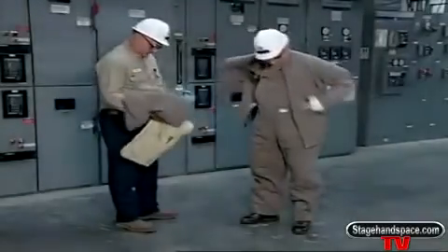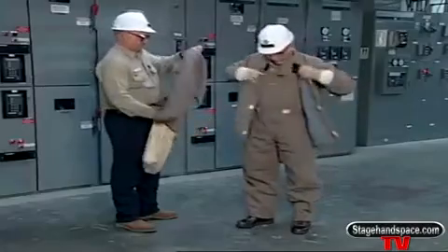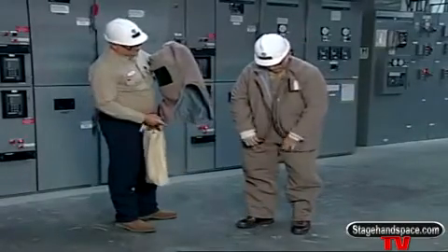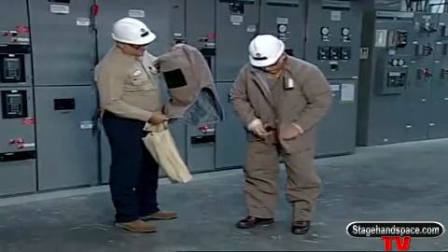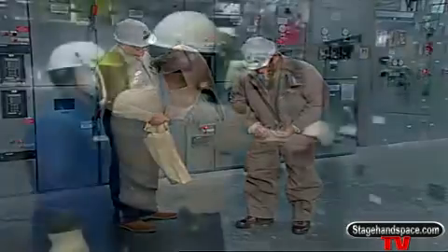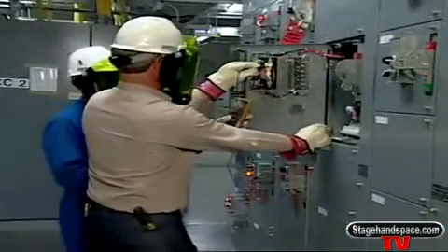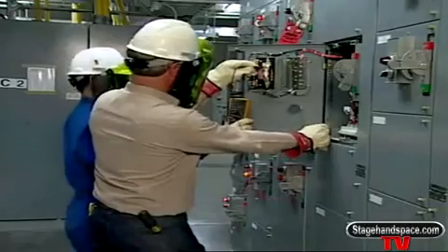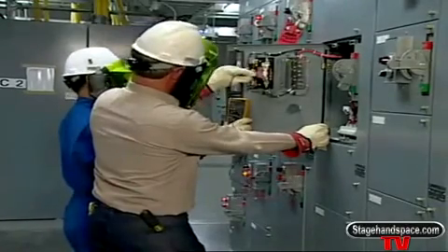Personal protective clothing and equipment must be provided and used when work is performed in areas where there are electrical hazards. The equipment must be maintained in a safe and reliable condition and visually inspected before each use. When flame-resistant clothing is worn, it must cover all ignitable clothing and allow for movement and visibility.